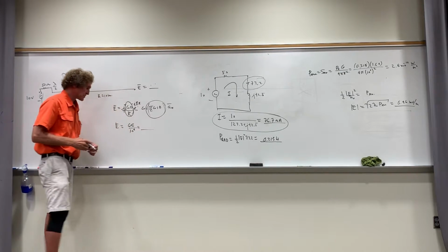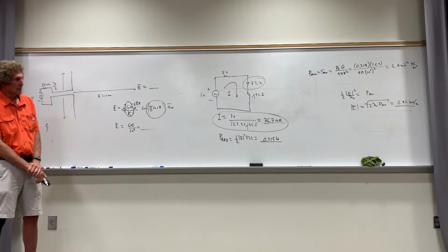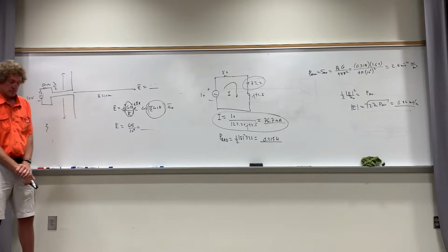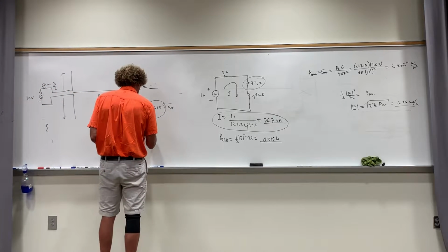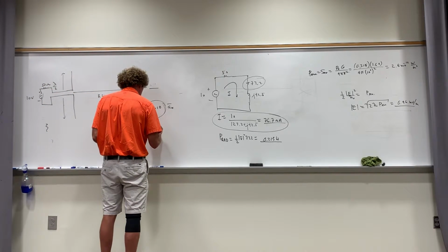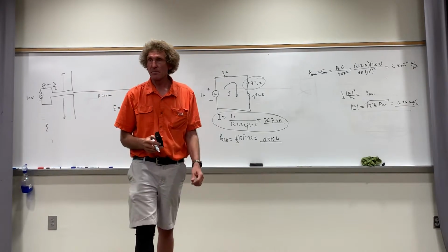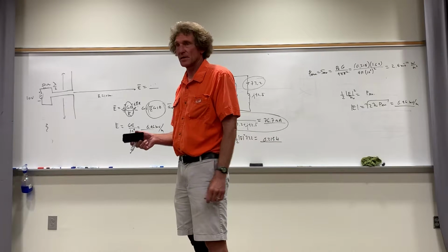Calculate that for me. The I is that value, 76.7 milliamps. Yep, 0.46 millivolts per meter. Now you notice this is a lot easier to do. It's one step, or really 2 steps: calculate I and then take that times 60 over 10 to the 4th.